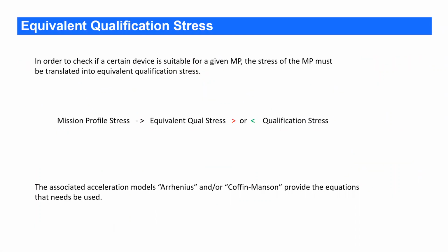Okay. Now, if you have a mission profile, you want to understand what is the equivalent stress that this mission profile is presenting. And then you want to understand, is this equivalent stress more or less than the original qualification stress?